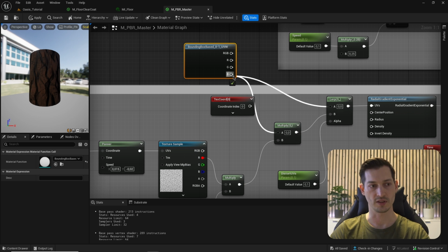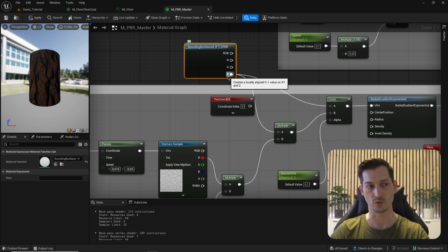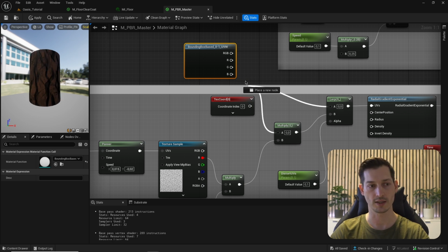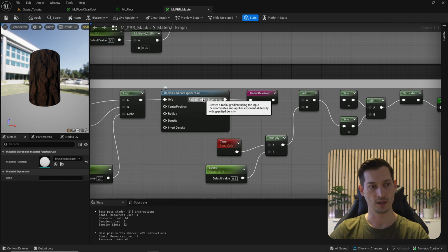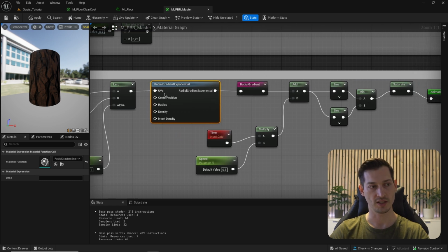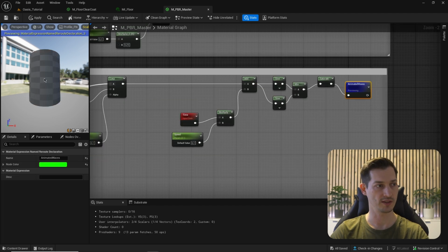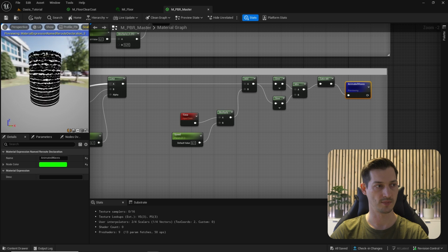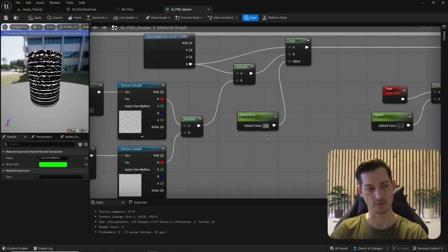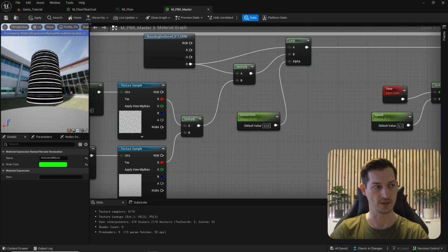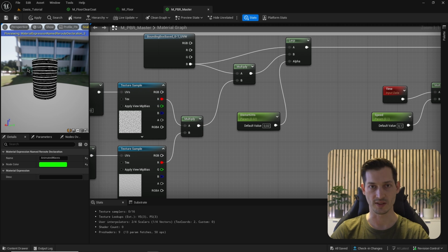So instead of the texture coordinates, I'm just going to connect this to B. By the way, if you want to reconnect existing node connections, you can hold down the Control key, left click and drag, and then you can reconnect them without losing the connections. Now instead of the gradient, I'm just going to connect this directly to the add of the time, and the animated waves, let's start previewing this, should now go downwards. Let's adjust the distort UVs to, let's say, 0.02. Now it's not as strong.